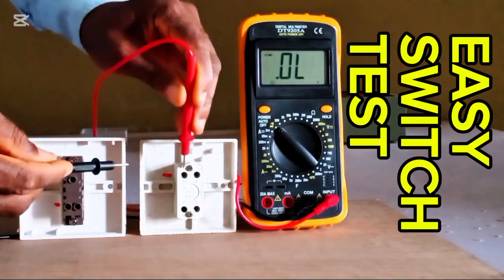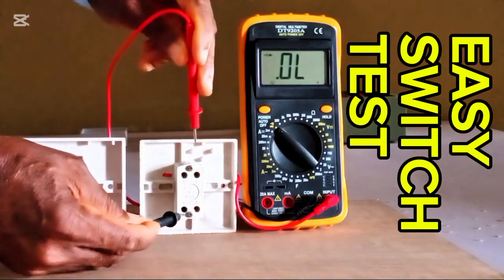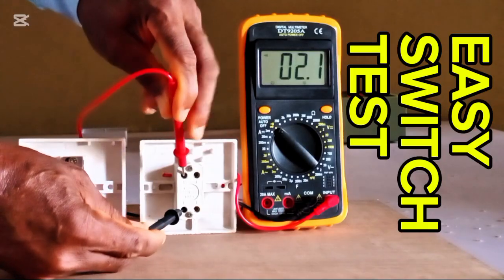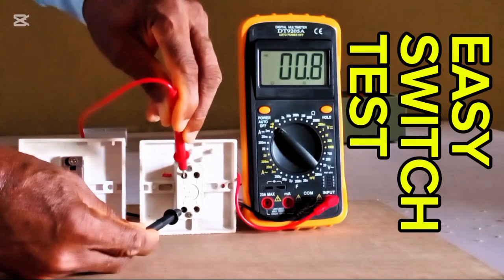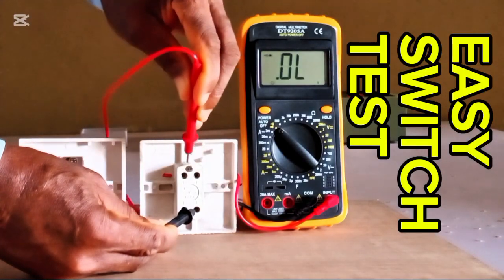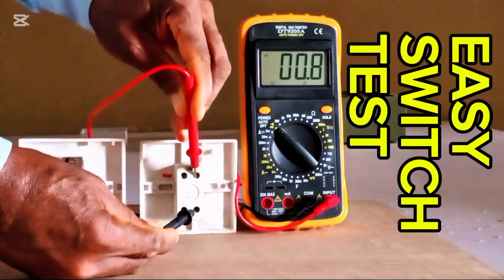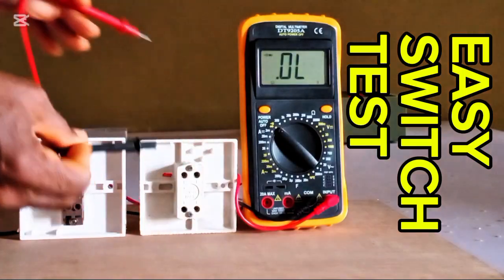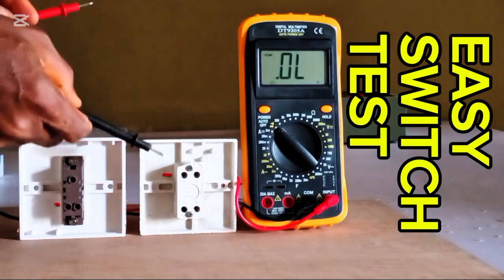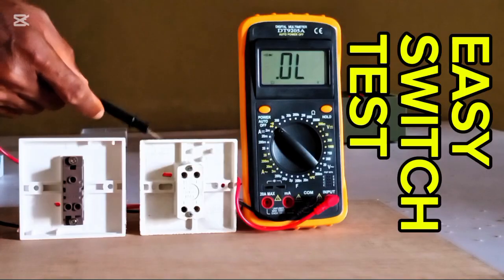All right. First, let's test this diagonal. You see, these two diagonals that initially read are now open, so they cannot read. Let's test the verticals and see. Good. The two verticals are reading in this second flip. So this tells you that in the first flip, diagonals made. In the second flip, verticals made. All right. So that is the design of this type of intermediate switch.